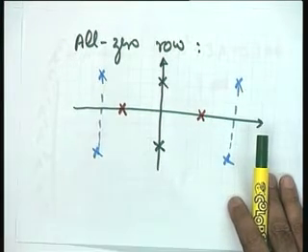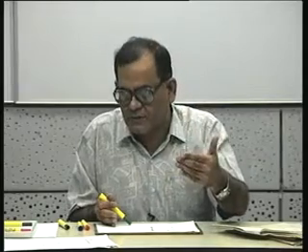The auxiliary polynomial formulation will demand that the all 0 row will always be at an odd power of S. Please look at these equations. It cannot be an even power of S, because the symmetry involved here is going to give rise to an all 0 row. Though the proof is not being given, from the statement you try to conclude what the situations are which will give rise to an all 0 row.